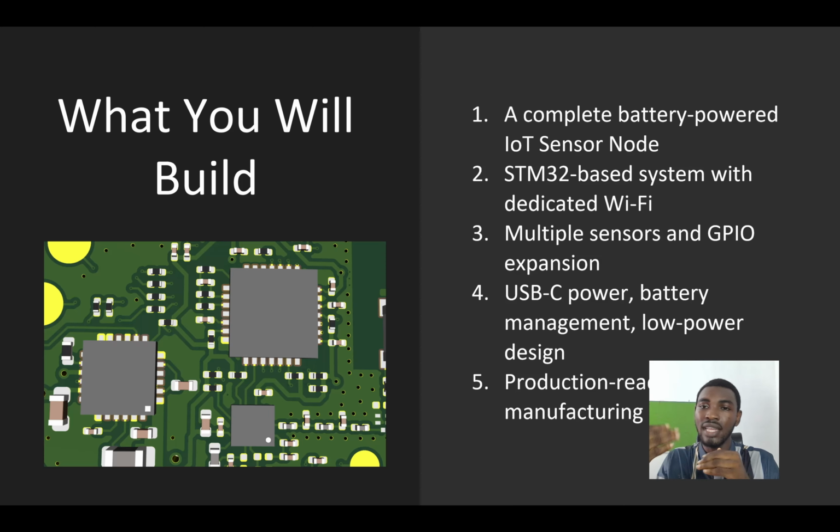Since it's an IoT product, it needs a connectivity option, and we use a dedicated Wi-Fi chip for that. Then we'll have multiple sensors, things like temperature sensors, humidity sensors, and accelerometers. Then USB power, battery management, and low power design. Lastly, a product-level PCB for manufacturing.